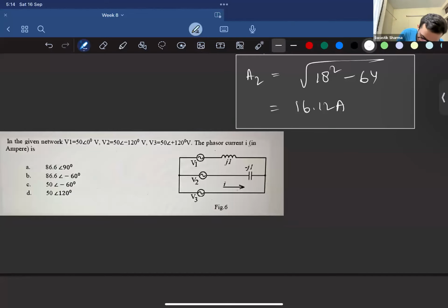So how can we solve the circuit? We can easily apply KCL to this point. All your circuit analysis theorems that we discussed are valid for single phase circuits as well. I'll tell you where they are not applicable once we reach that stage, but KCL and KVL are applicable to single phase or three phase circuits.